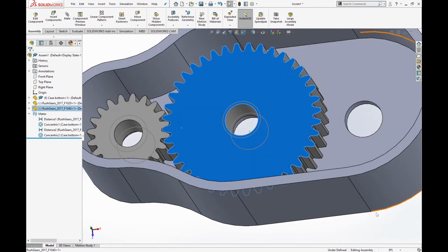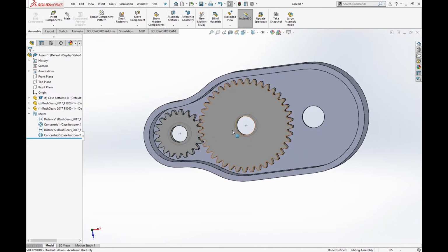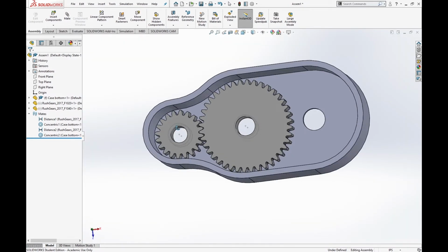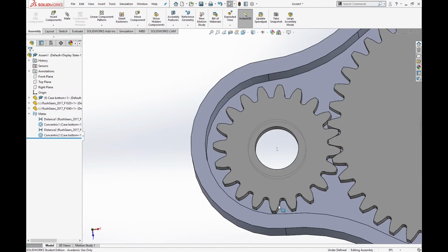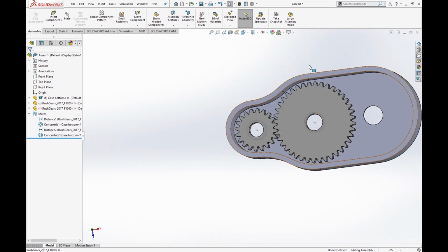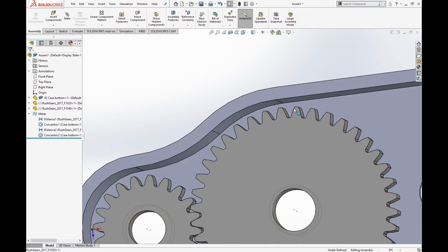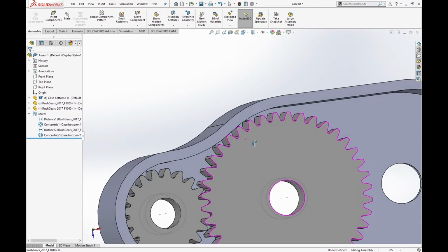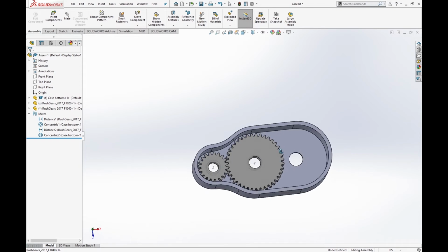All right, so we have that gear there. So now we know that this one is good. This one is good. I didn't mention earlier, but as you can see, because we left that 1/8 inch on this side and all the way around, there's plenty of clearance all the way around our gear. Some of you guys might be like, why are you doing the whole 1/8 inch? That might be too much. It's just what we've used. Leave it in the comments if you guys use something crazier than that. More power to you if your gearboxes work and you leave less. I'd be interested to see how small you can get.